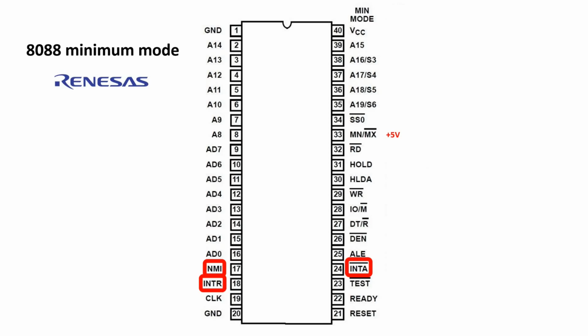If we compare it to something like the 6502, it has an IRQ, which is almost identical to INTR, but it's active low. That goes to a fixed location and there's no vector capability. So it was very thoughtful of Intel to design the chip to go along with the 8088 to give us a quite sophisticated interrupt facility where we can have multiple interrupts and going directly to the routine where they're required. On something like a 6502, if IRQ is shared, you've got to do some software polling of the peripherals to find out which peripheral caused the interrupt.